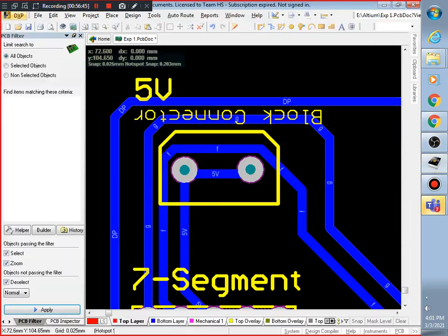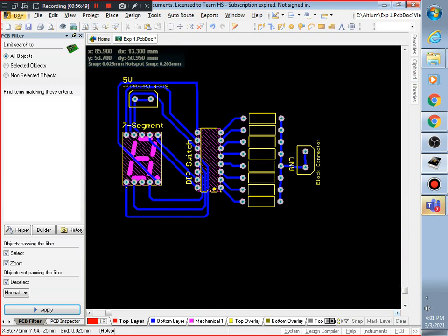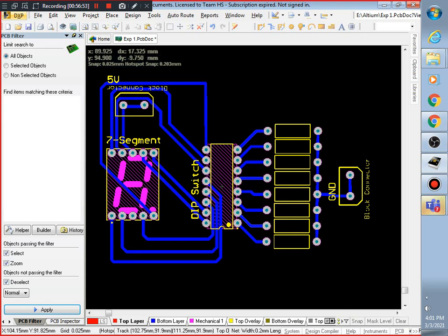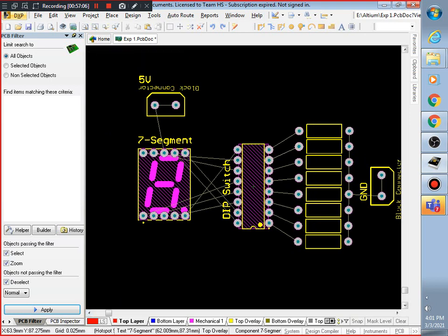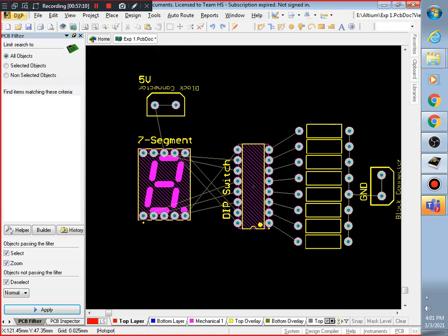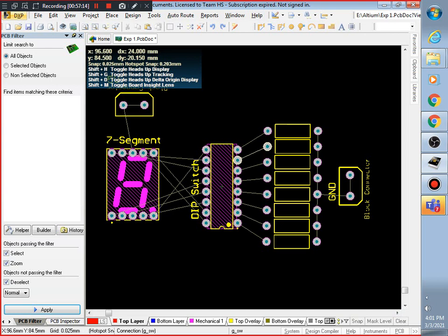Back to the software. What I have done, you can see I have shared this all overall, and this PCB has been rerouted by this auto route button. I will just click on reroute and just undo. Okay, this was that point where all the filters have been done, the pads have been changed to 2 mm and all that stuff has been done. Now I want to route it. I am going to ask the software to do it for me.